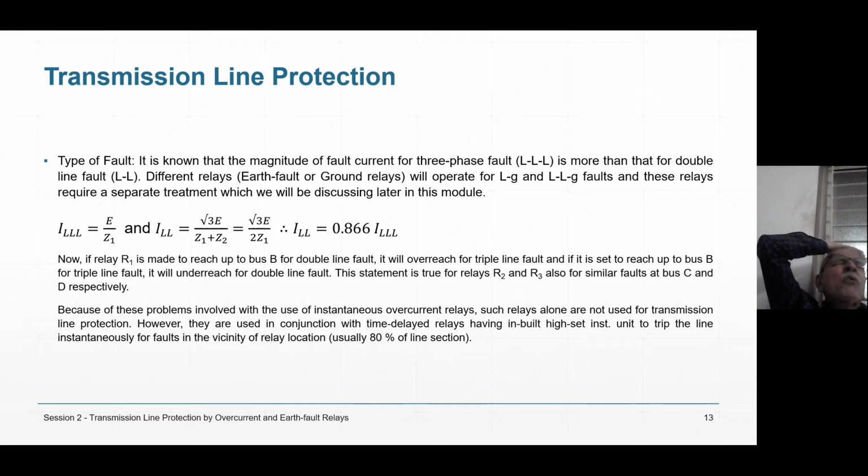The time for which a generator can remain in asynchronous condition depends upon its inertia constant. It can remain in asynchronous conditions for say 12 cycles, but you are tripping in 3 cycles. You are not waiting for the generator. You are not exploiting the capacity of the generator to work in asynchronous conditions. So that also you are not doing.